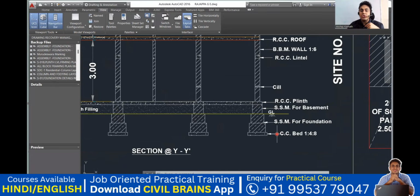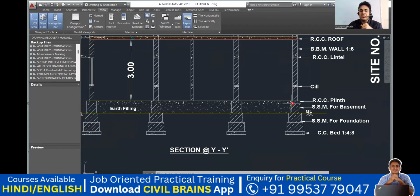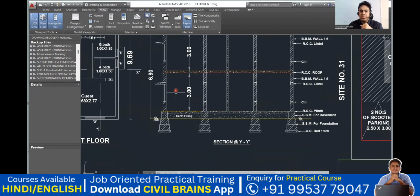And after that, we are going to do the masonry work. Stone masonry work. Soon after that, we are going to construct with the help of laterite stone. In the local construction, we make use of stones, and we construct that up to the ground level. Then after that, we are going to put the plinth beam. So this is RCC for the plinth. You're going to put the RCC for the plinth beam, and then we come to the ground floor. So this is my ground floor.